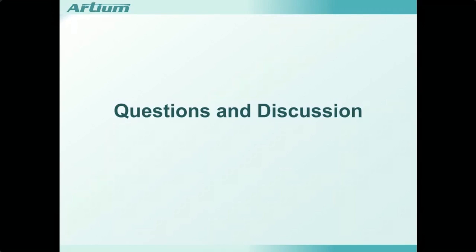I didn't quite hear it. Okay. The second part is what flow frequency can be resolved with 90% amplitude matching? I'm not sure how the amplitude matching comes in, but the flow frequency that can be resolved, I'll attempt to answer that. It depends on two things. One, it depends on the seeding rate. So if you have sufficient seed, you'll have a high enough data rate to resolve the frequencies in the flow.